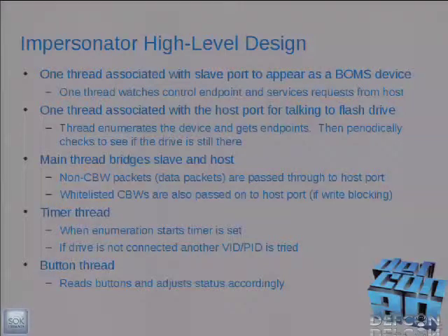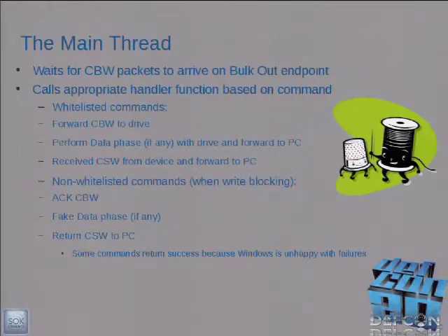Also, there's a timer thread, and what the timer thread does is if you're in the automatic mode, whenever the PC asks for a device descriptor, it says, oh, someone's trying to talk to me, and it starts a timer. If they stop talking to you after a second, and they don't ask for additional descriptors, it says, oh, someone's blocking me. I'll go to the next one. And that's how that works. And there's also a thread for reading the buttons that come in.